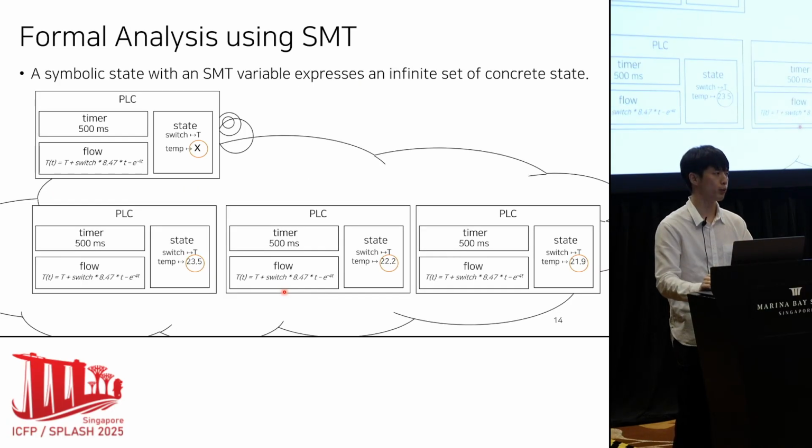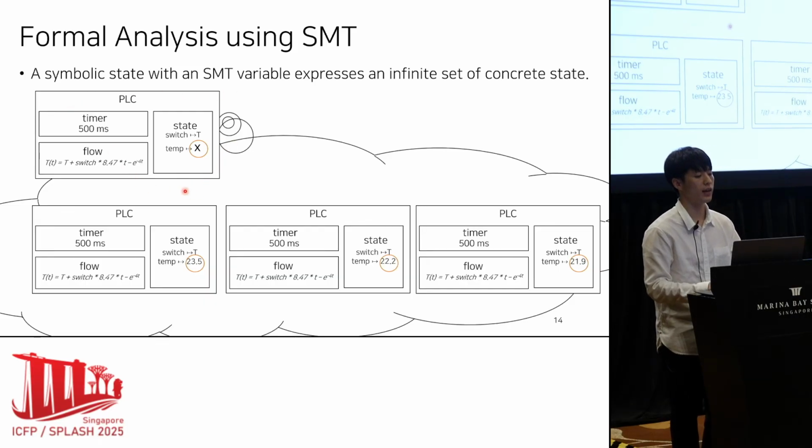Now let me talk about the formal analysis. Formal analysis, such as model checking, is possible with our unified semantics because they are executable. Note that our semantics is symbolic. That means we can have a symbolic state that can represent an infinite number of concrete states. For example, here we have a symbolic state with an SMT variable x that represents the temperature. It can represent an infinite number of PLC objects with any temperature values.